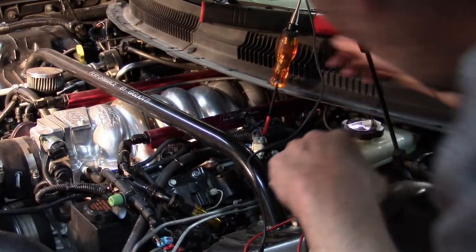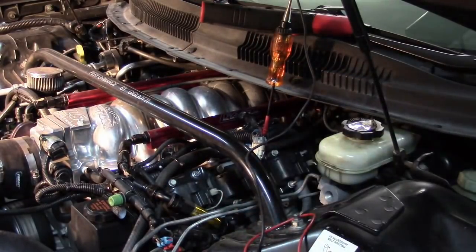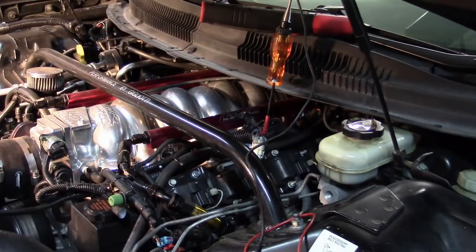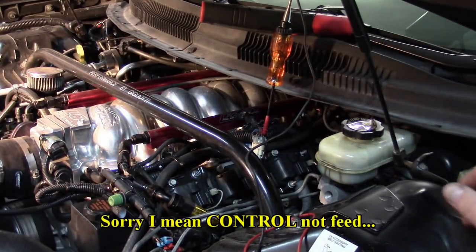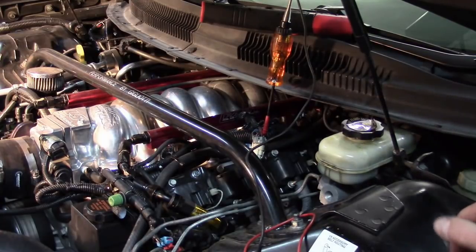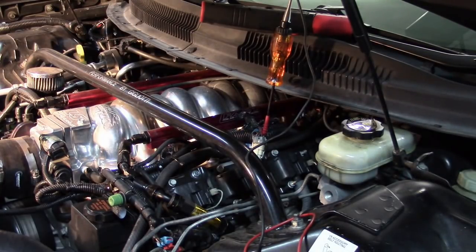Okay, so that confirms. Again, it's okay to make mistakes. I guessed that the red wire was constant positive. Obviously, it is feed. Now, we don't know which coil that feeds. And admittedly, that would be where a wiring diagram would come in handy.